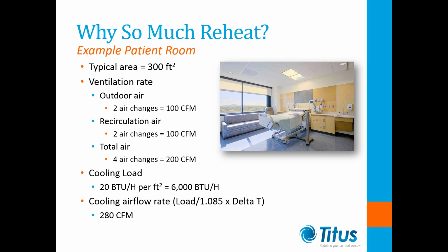Based on the moderate cooling load of 20 BTUs per hour per square foot, the total cooling load will be 6,000 BTUs per hour. Using this simple equation, we can calculate that 280 CFM is required to cool the space during its peak load condition.